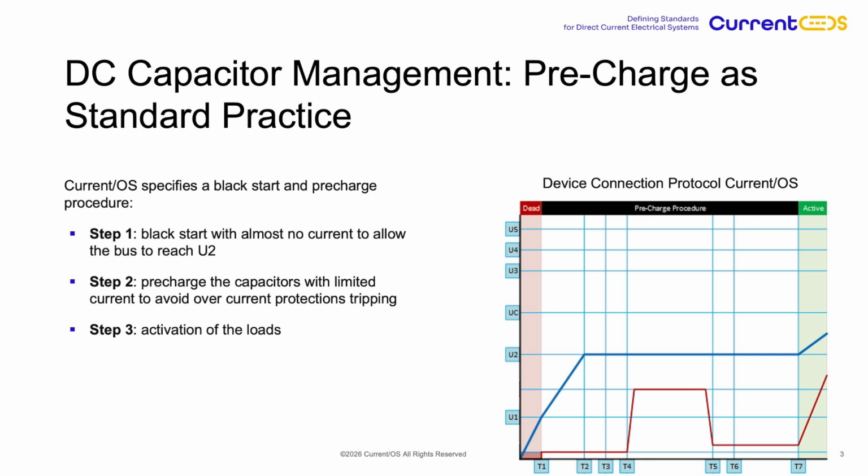Maintenance also becomes more complex. Because all equipment depends on the same pre-charger, the entire group of loads generally needs to be disconnected or shut down simultaneously. For these reasons, centralized pre-charging is typically reserved for very specific applications, where the equipment configuration is fixed and changes are expected to be rare.